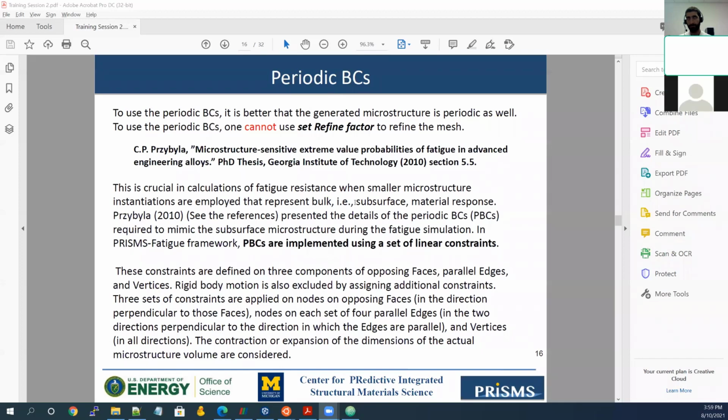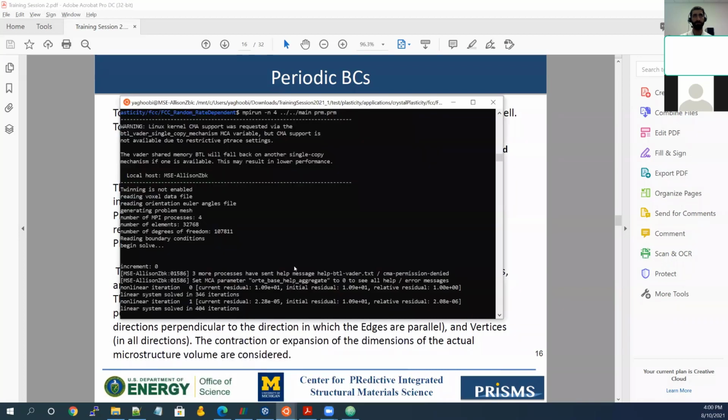Yeah. So basically, what I'm trying to do is implement a dislocation-based constitutive model that includes the effects of both statistically stored and geometrically necessary dislocations. So there will be something like a Kocks-Mecking law for the statistically stored dislocations, whereas for the geometrically necessary dislocations, it will be computed.